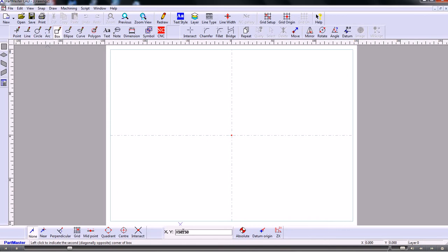and press enter again. So the way that the CAD system works is that we stay in one particular mode until we change from one operation to another. So supposing I wanted to now put in a circle, and I go back to the command window here and I type in the coordinates of the circle. So if I say x20, y20, okay, so that's taken the commands from the datum point.